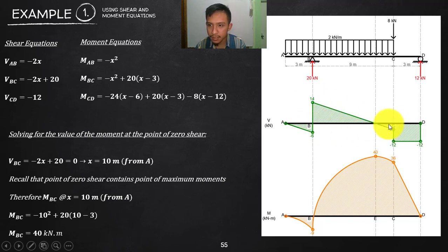14 plus 4 is 18. So negative 18 divided by 9 is -2. The slope is -2. So that is a straight line. Again, this is flat. It will go first degree. And then second here, there is no loading, so that will be flat. And then next will be first degree.